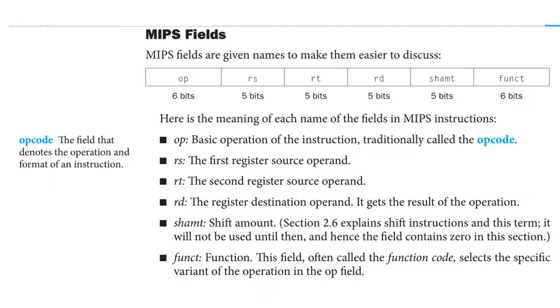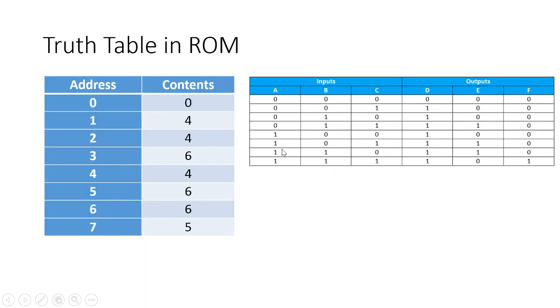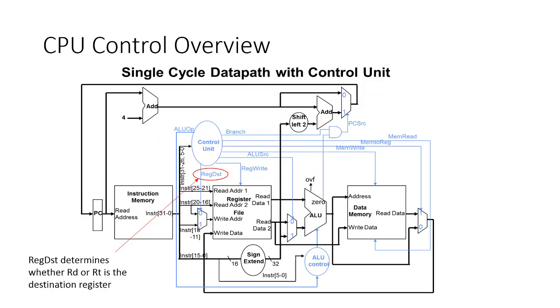The R type breaks up each of the 32 bits of the instruction into different parts, as it states here, so that's easy for use. One of them we've talked about previously, and it mentions in chapter 4, is the opcode. We've talked about that a lot. And the function. The opcode and function bits interact with each other. Well, that's what this example we've been talking through is. That's why the opcode and the function codes exist in MIPS, for this reason.